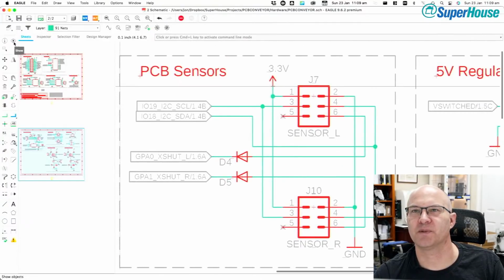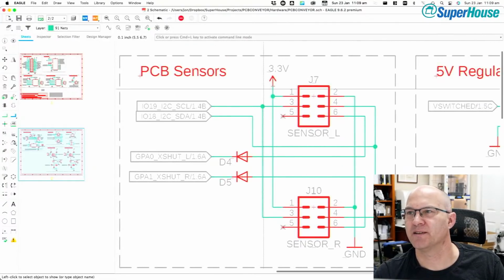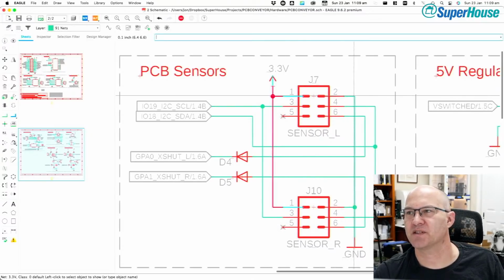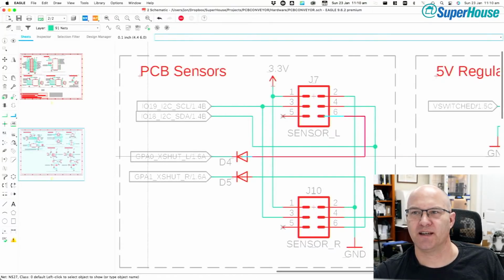It's a little bit confusing because of the way this is done, but what we've got going to the time of flight sensors is 3.3 volts and ground, kind of obvious. Then we have I2C, we've got SCL and SDA going to them. And then there is another pin here, which is going through a diode, and it is called X shut.